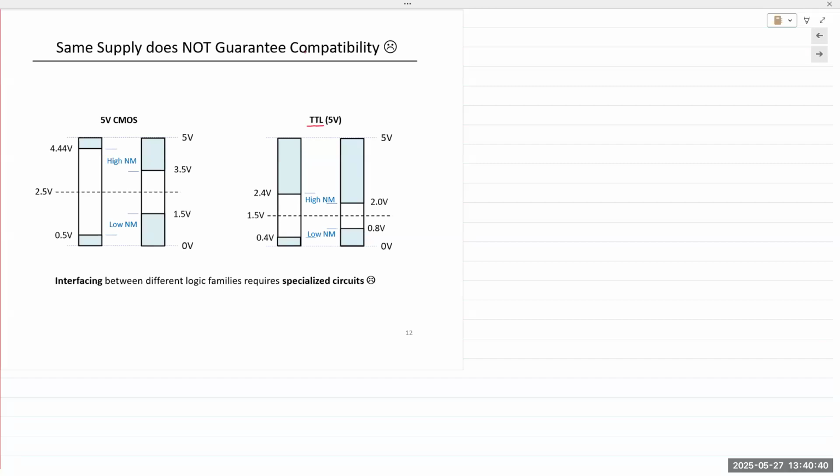Trigger level. But it stands for transistor-transistor logic. And CMOS, here, the word comes from complementary MOSFETs. So if you have MOSFETs, both NMOS and PMOS in the circuit, we say complementary MOS, CMOS design. TTL is if you use BJTs, bipolar junction transistors, and it's known as transistor logic.